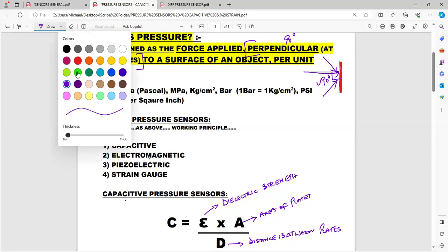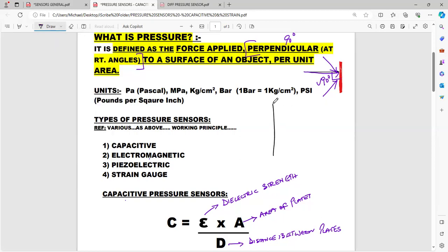Okay, sir. So let's see, this is your OWS tank. It's generally filled with seawater. And then you're going to be pumping your bilges from the bilge tank or whatever to that and then overboard. Let's say this is your overboard valve, and this is overboard. Generally you're going to be having two sensors. One sensor here, one sensor here.